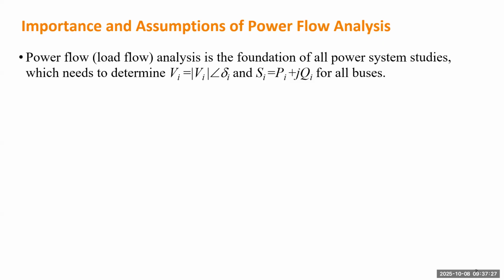Definitely, you can add some additional requirements. For instance, I know the power flows right now for the current system, but I want to open the line. If I open the line, definitely the current on the line will become 0. So the voltage on both sides of the line will change. So we need to recalculate the power flow, right? That also indicates some applications of power flow analysis.